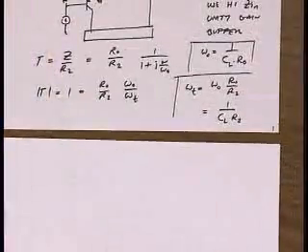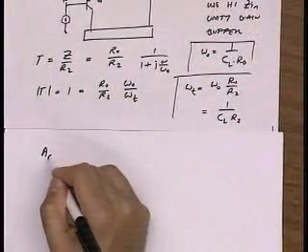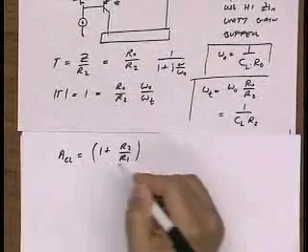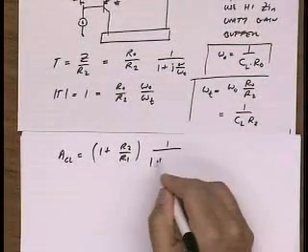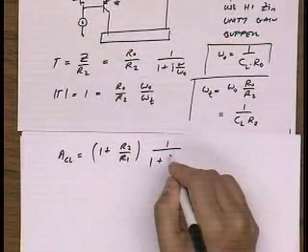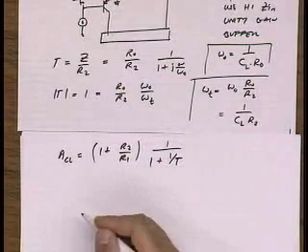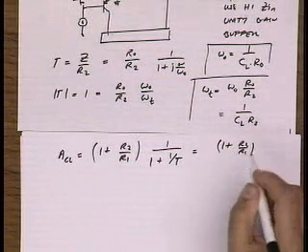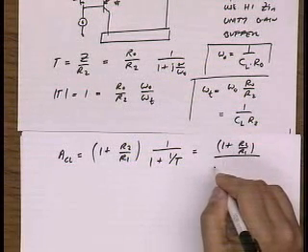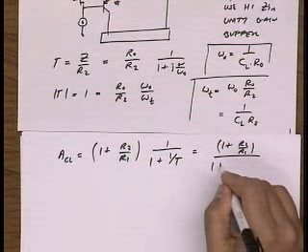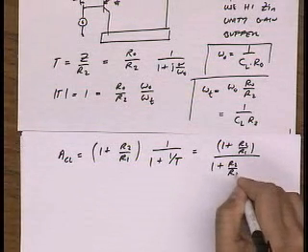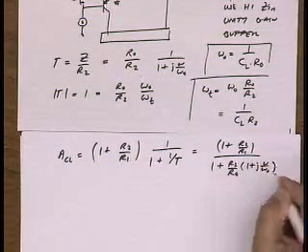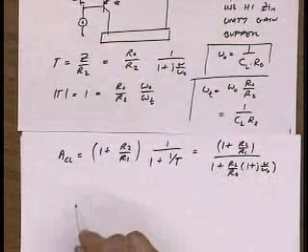Now likewise, last lecture we derived the closed loop gain, the exact gain, which is 1 over the feedback factor, times 1 over 1 plus 1 over t. And if we substitute, we get, again, that 1 over the feedback factor. If we multiply this out, we get R2 over R naught, 1 plus j omega over omega naught. This is just 1 over t here.